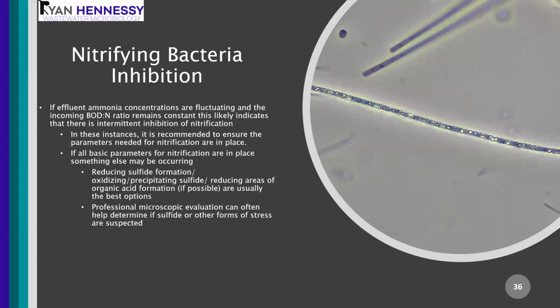If certain organic acids, generally the odd carbon propionic acid, are present at high enough abundance, they tend to be really difficult for the nitrifying bacteria, especially the NOBs, and that's where you tend to run into a lot of problems.